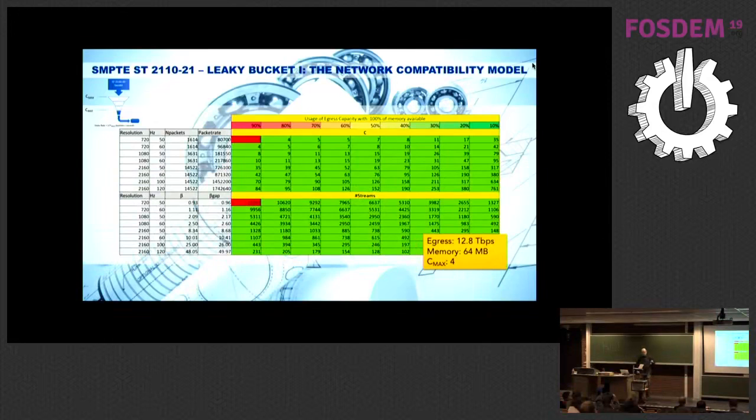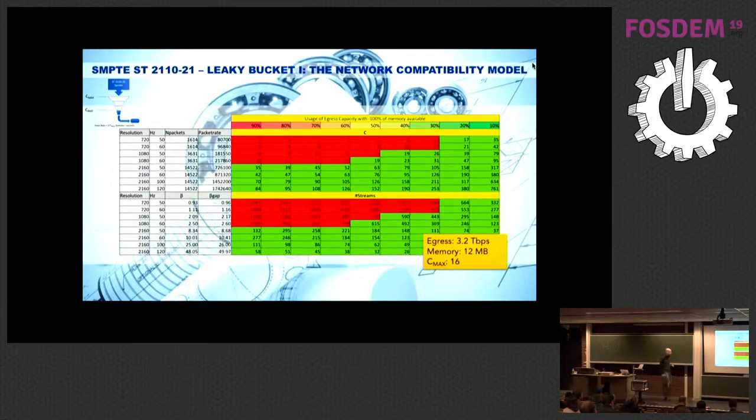Now, if you would say we move from this FPGA implementation towards a software implementation, which has a little bit more jitter, it could burst up to 16 packets in that buffer, then you could see something like this. Quite interesting, right? At 90%, not good. You're starting to drop packets anyway and your application will fail.